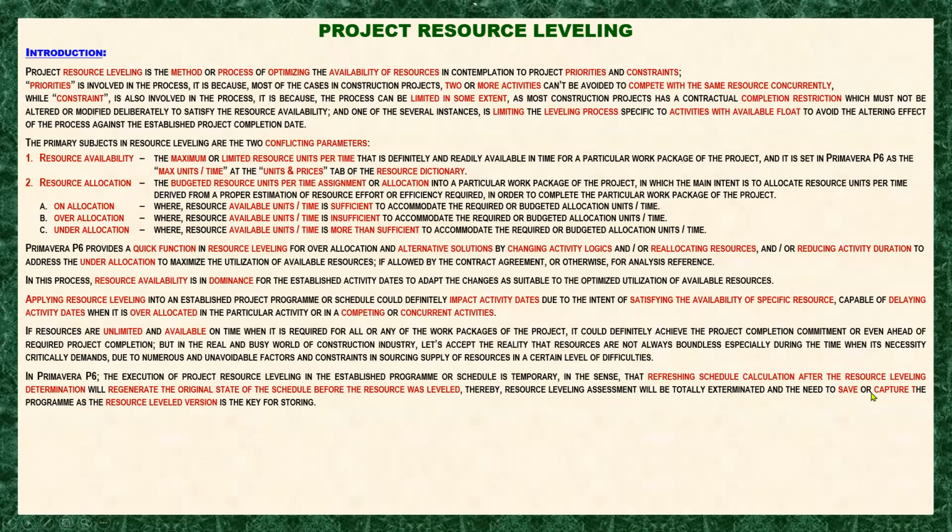So the need to save or capture the program as the resource-leveled version is key for storing. That means when you run resource leveling on your schedule or project and you know that it is already final, don't run the scheduling, because you will be running again the resource leveling on your project.